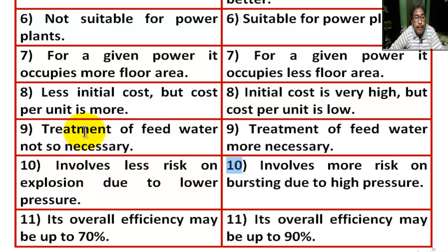Number 9, for fire tube boiler, treatment of feed water not so necessary. In fire tube boiler, the treatment of feed water is not very essential, as overheating due to scale formation cannot burst the thick wall. Okay.